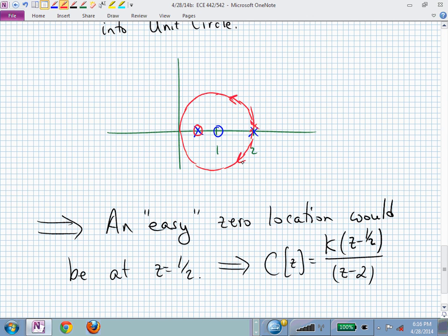So that now my root locus, to sketch that, I would just have... am I done with my root locus? You have to remember that I like to go towards zeros. I've virtually erased that red and blue X, but I still have a 0 here that I'm moving towards, and I have my 0 at infinity. You said my pole 0 excess was 1, so that's now what my root locus diagram looks like.